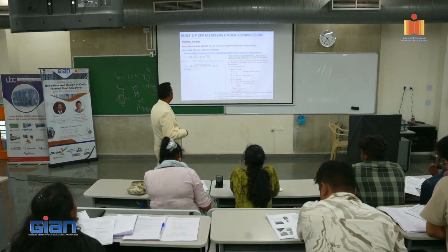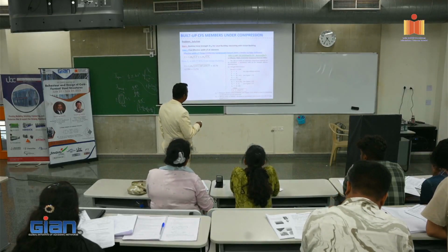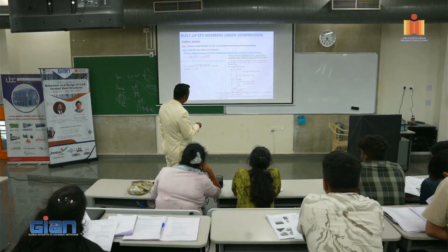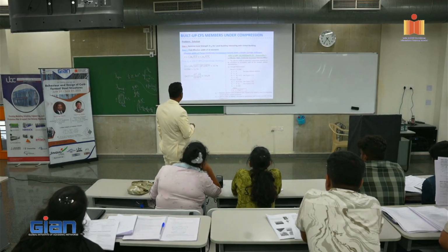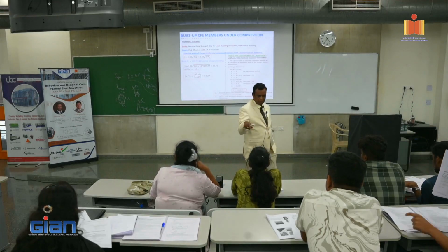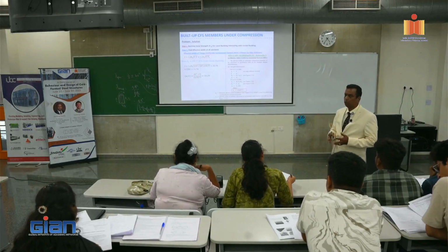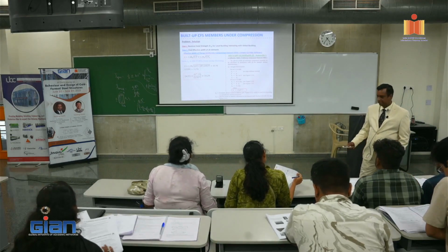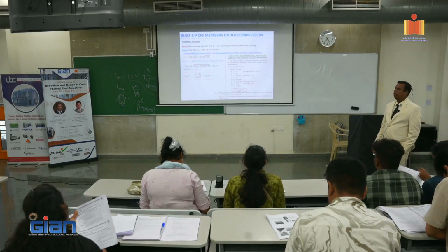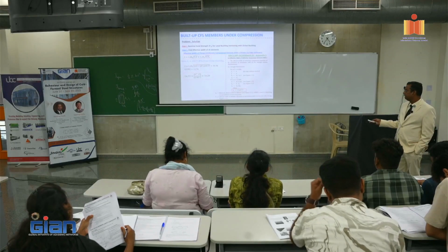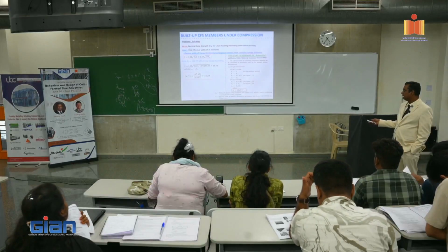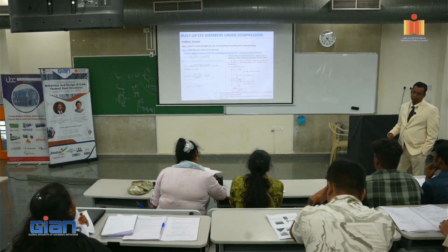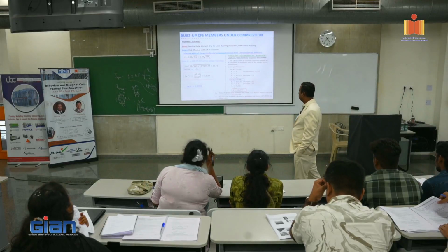So we have to calculate this. Our objective is to find out which equation to use, the top equation or the bottom equation. To find that out, we calculate W by t and check whether it is less than or equal to 0.328S. When you go back to the previous one, you will see that the flat width is 67.12, divided by thickness 1.957. You get 34.29. That's the W by t. 34.29 is obviously greater than 11.74, so we come to this part. This is the equation that we should use. So when we use this equation, what do we do here?